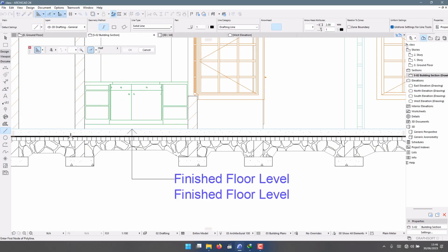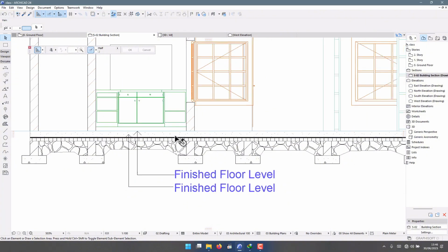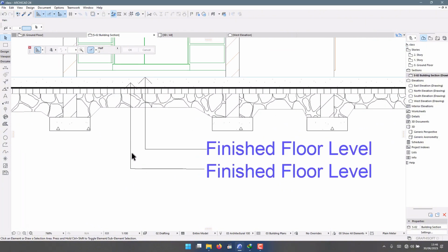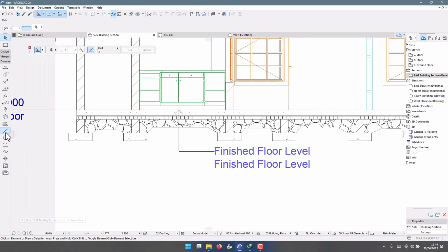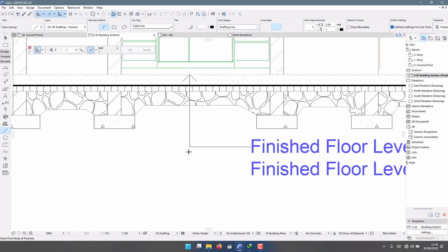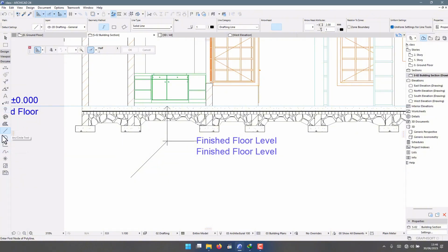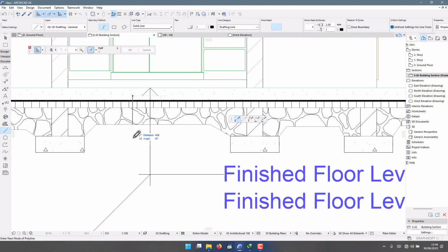If you want, sometimes if I have more time, you can make sure this line and this one are the same. To do that, you just come here and draw a line at 45 degrees, which is 135. Then now if I drop a line like this, it touches this and goes this way.